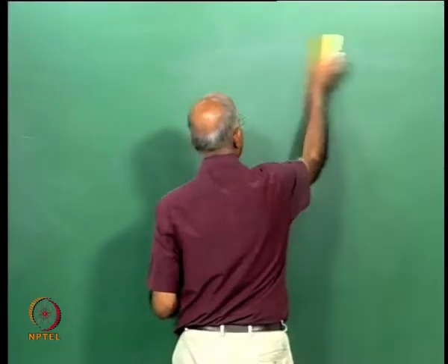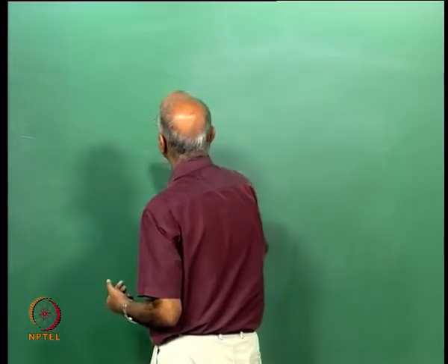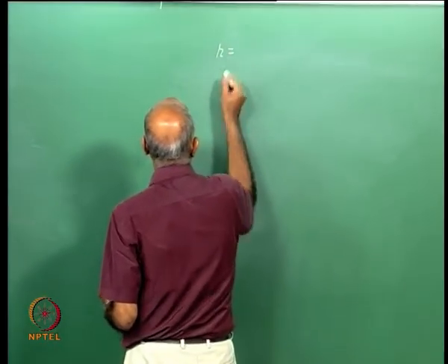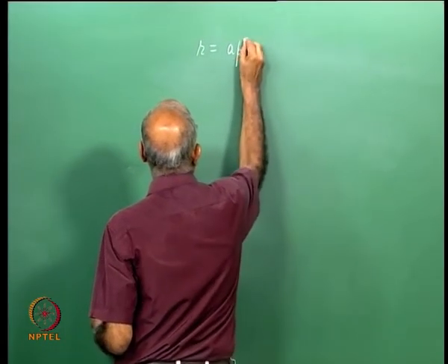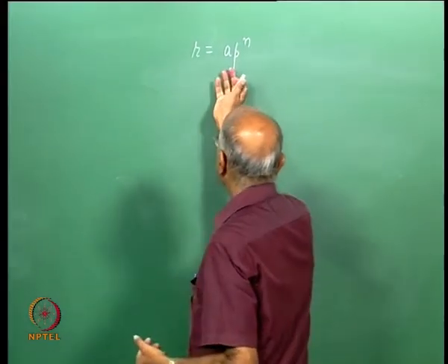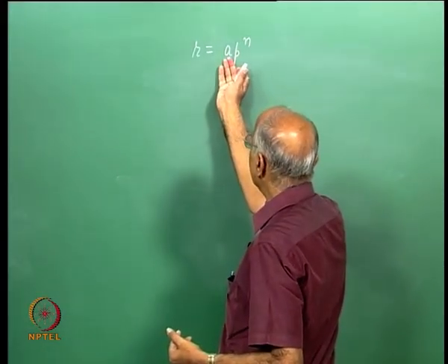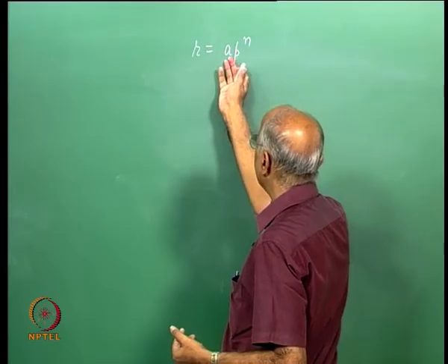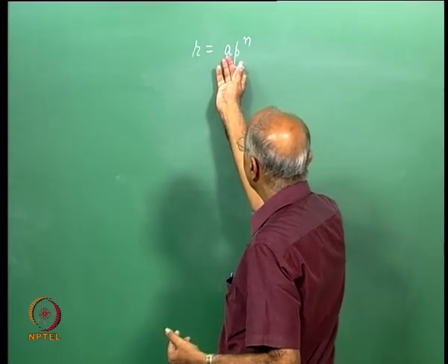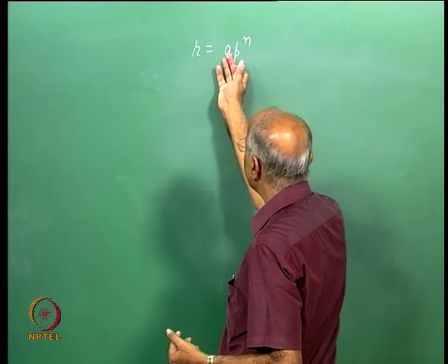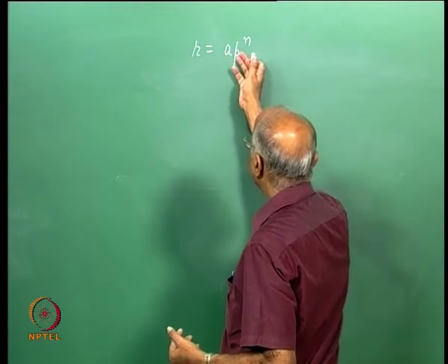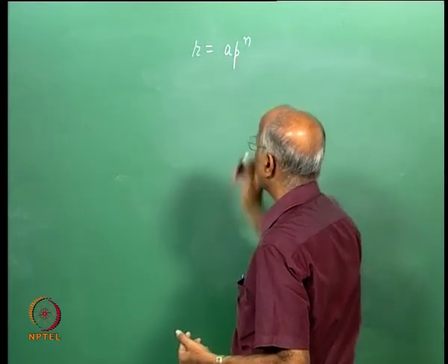Let me again repeat this point. What is it we have said? We said that the burn rate of a double base propellant can be written as R = aP^n, where a is a factor which considers all factors other than pressure, like temperature of the gases, maybe T1, maybe the surface temperature, maybe the activation energy and all that, and pressure is directly taken to a power n.